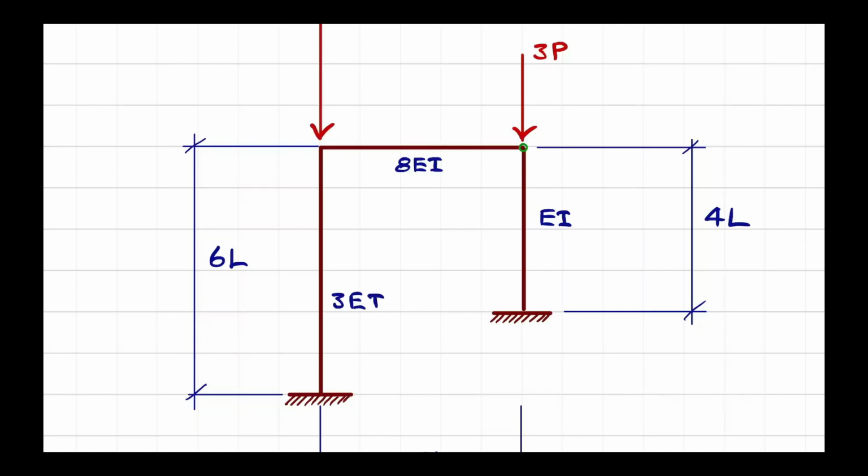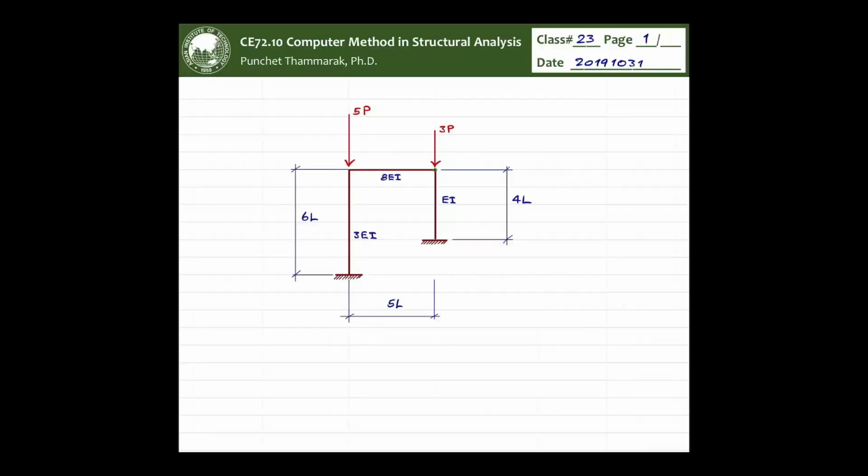You apply the load to this system, you do not cause any deformation. Well, you might say that axial deformation will be there, but you will not cause any lateral deformations. Okay, so the structure just looks intact. So you don't see anything until you reach the buckling load, and then suddenly the structure collapses down on the floor.